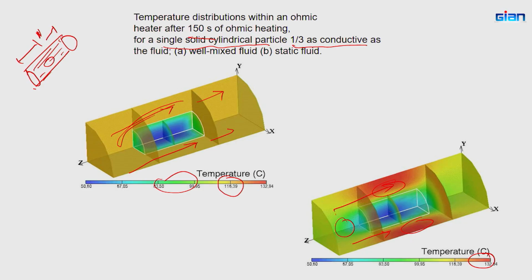So, in other words, you have to understand how well the electrical conductivity in the liquid and solid is mixed uniformly, so that for the current it looks like the same mass, whether it is a liquid or solid. If it is the same electrical conductivity, it is going to heat much more uniformly, whereas when the value is different, then they are going to have different temperature distribution.